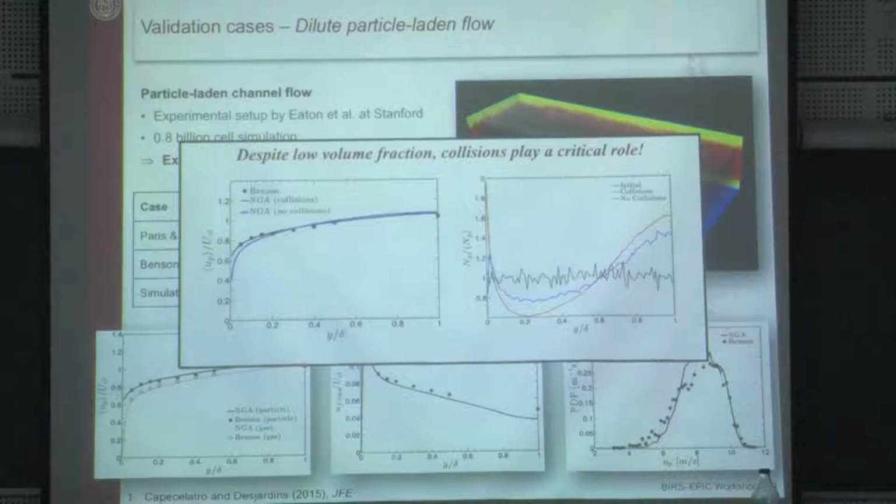This is turbophoresis. Same mechanism on the micro scale as the Maxey-Riley mechanism, but now integrated from the perspective of a wall-bounded turbulent flow. Let's look at the overall dynamics, how are the particles migrating. Okay, so that explains this dip. That also explains why we need collisions.